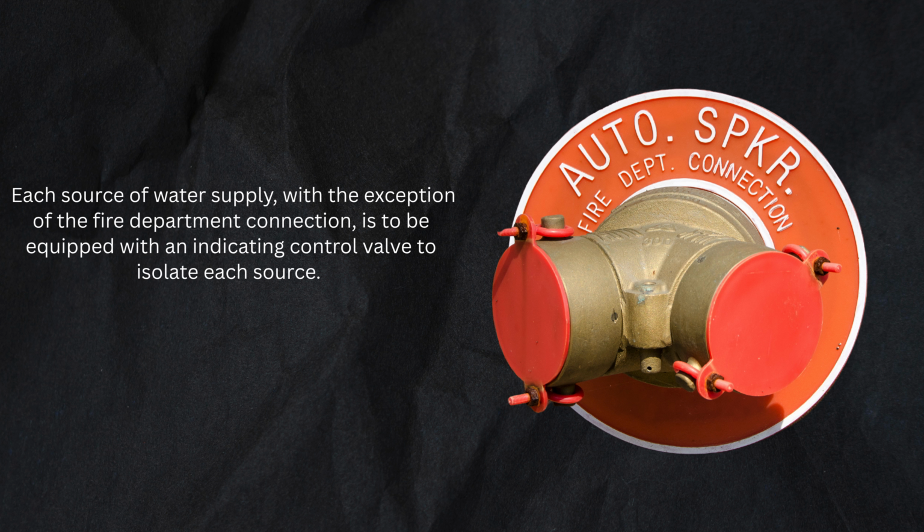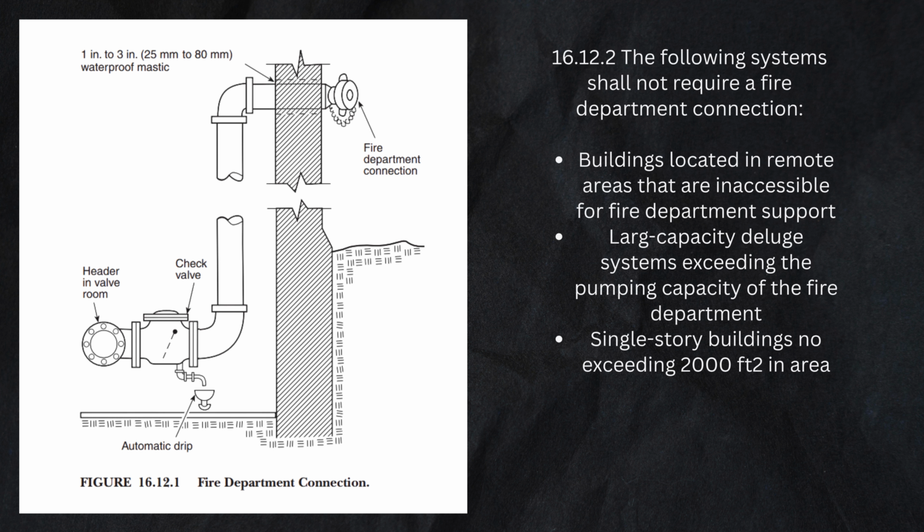Fire department connections shall be equipped with approved plugs or caps, properly secured and arranged for easy removal by fire departments. Each source of water supply, with the exception of the fire department connection, is to be equipped with an indicating control valve to isolate each source.